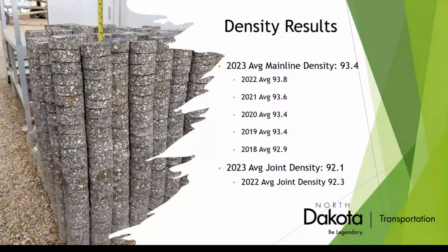And Kurt, I know, is on here, but he can attest to that because the Grand Forks District did a lot of work from 2016 to 2020, just running cores, reference cores, and doing core densities and bulks on what kind of densities, and finding 87s and 88s wasn't too hard to find. And that was using the Maryland joint, longitudinal, but basically butt joints for longitudinal joints. So that's a really good success story.